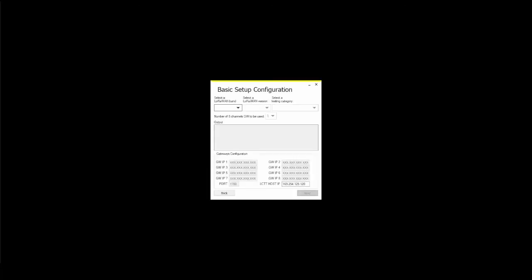After selecting the gateway, the LCTT requires some details about your setup to be able to create the configuration file for the gateway. Those parameters are the LoRaWAN regions you are interested in, the LoRaWAN version, and the testing purpose. Here, the certification testing is the option to be used by the authorized test houses, and this is only available if some requirements are fulfilled. For example, you need a 64-channel gateway to test a fixed channel region. On the other side, the pre-testing option is available with any setup.